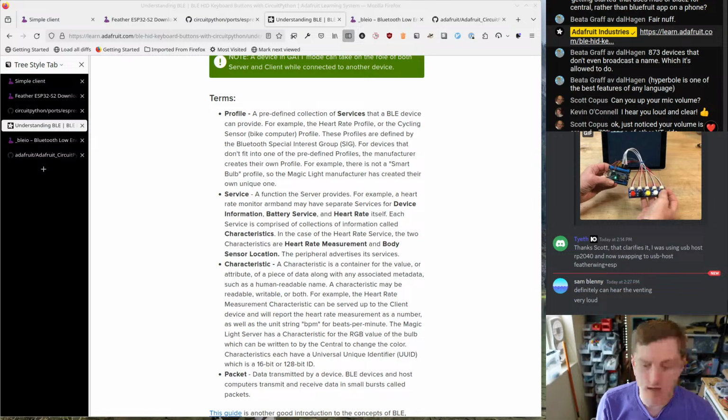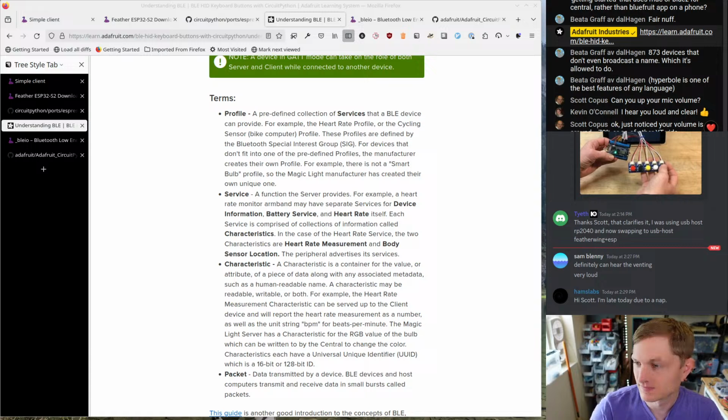So I've been trying to get that all working on ESP. Now, if you want your ESP to act like a keyboard, usually your central will also want you to pair and bond before you do that, so that you're not sending keystrokes unencrypted. And that is not something that we currently support. That's something to do later when I get back.